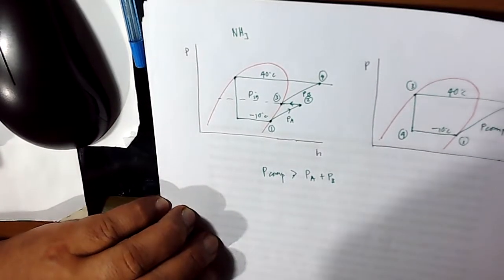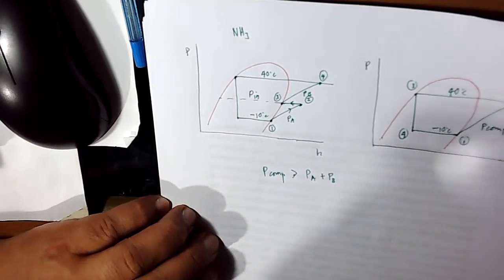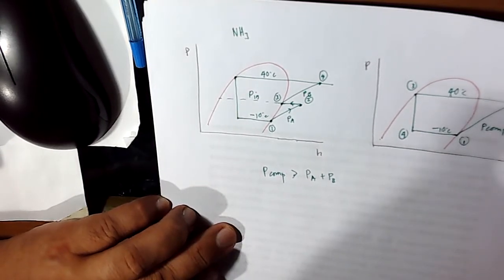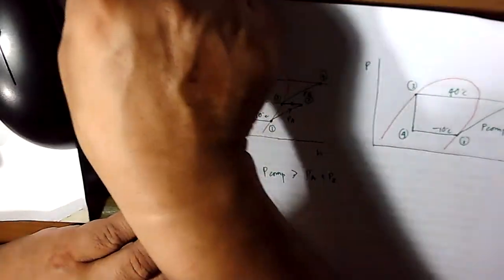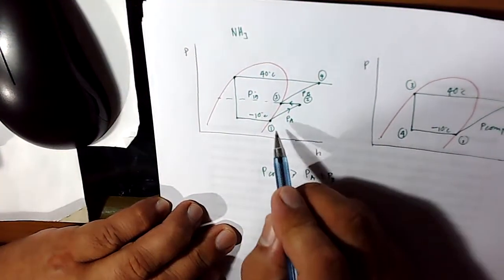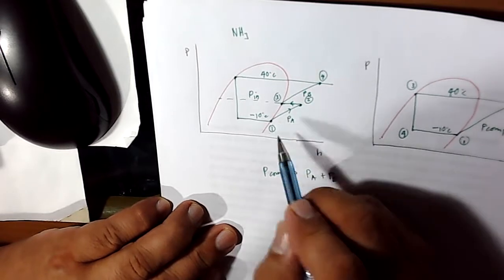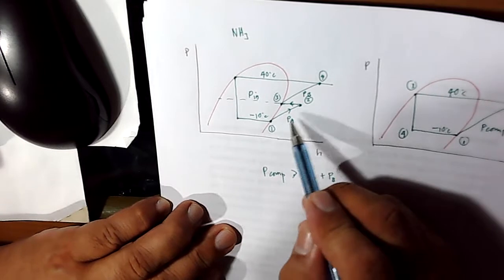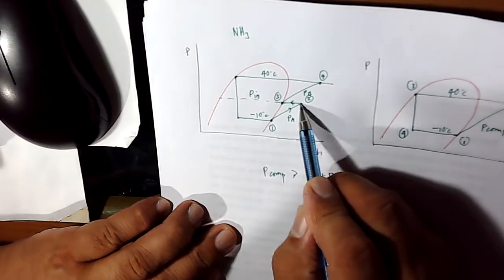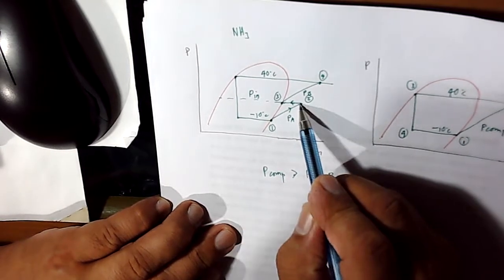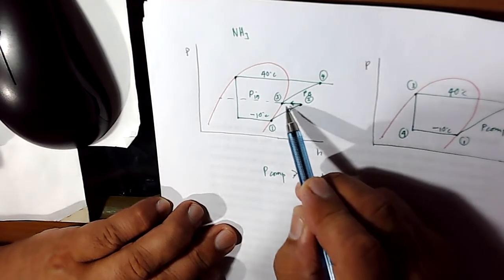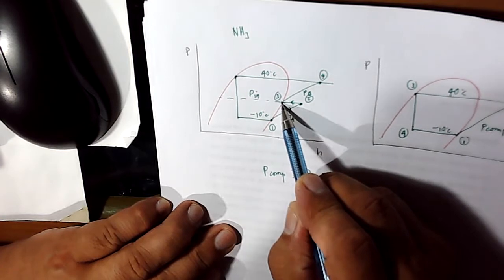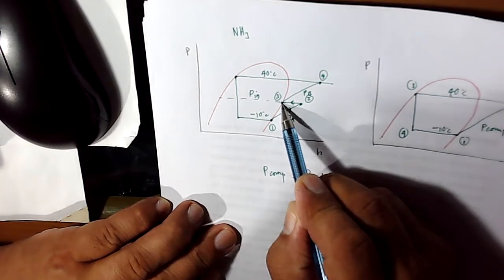Okay, last time we had the intercooler. We use a water-cooled heat exchanger to absorb the heat coming from the low stage compressor going to the second stage. But before entering the second stage compressor, the superheated refrigerant coming from the low stage compressor is changed to saturated vapor.